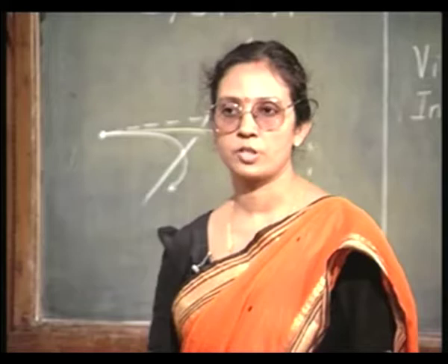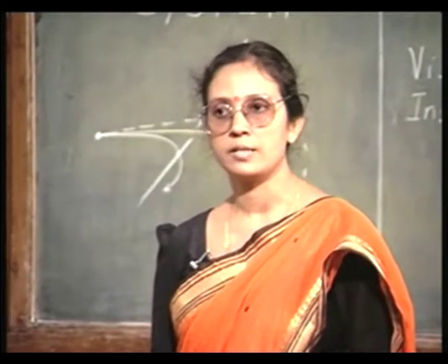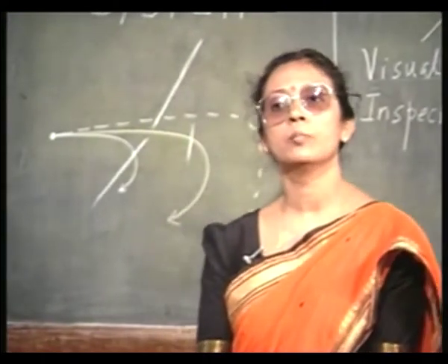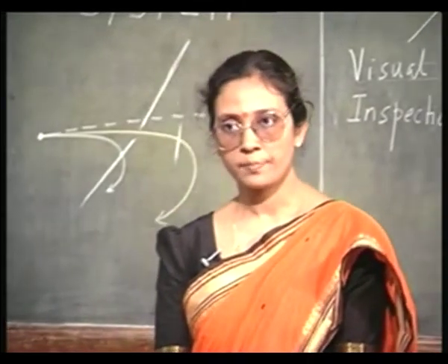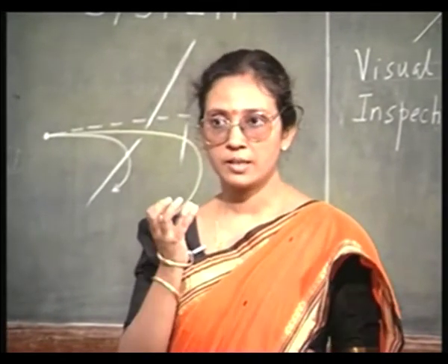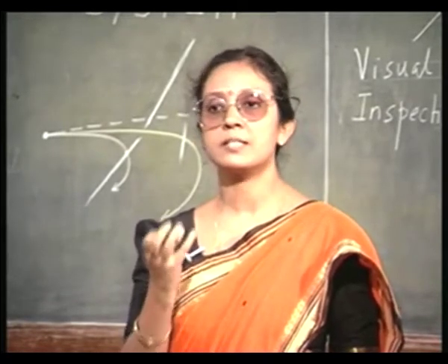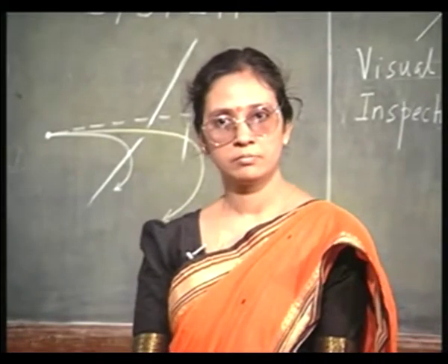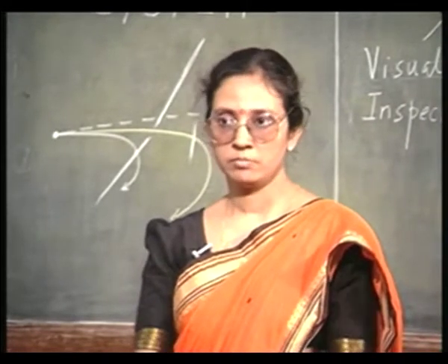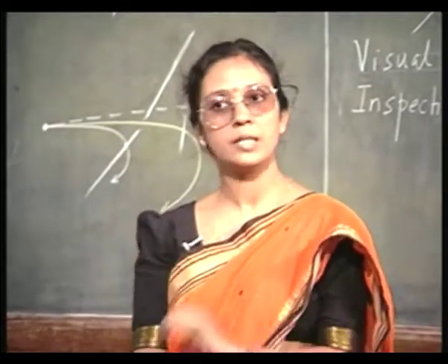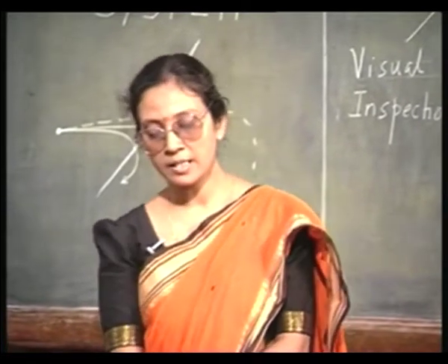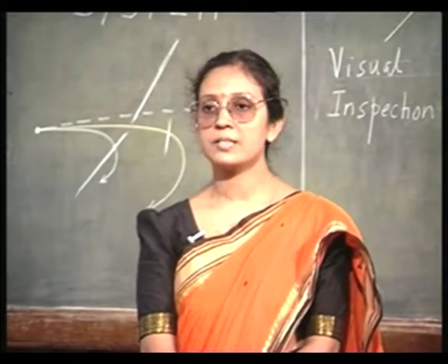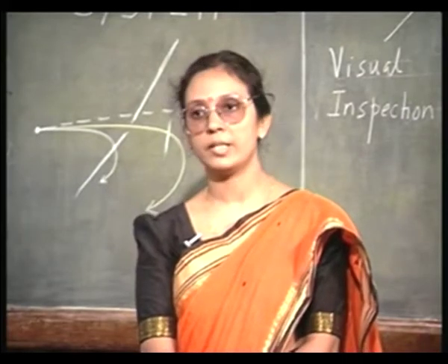It hits the substrate, undergoes collision with the lattice atoms. So, during each collision, it is transferring a relatively small amount of energy. And because this incident ion in itself is a light ion, at each collision it is getting displaced through a large scattering angle, right. The lattice atom is much heavier compared to the incident ion. So, the incident ion is getting deflected by a large scattering angle, but it is transferring only relatively less amount of energy.